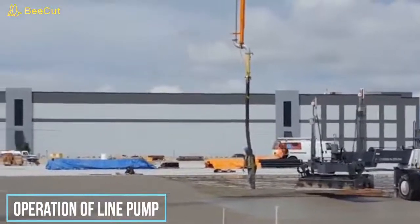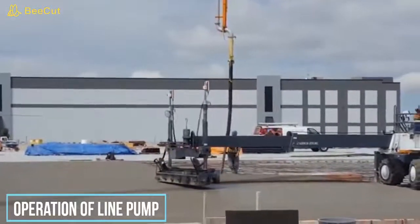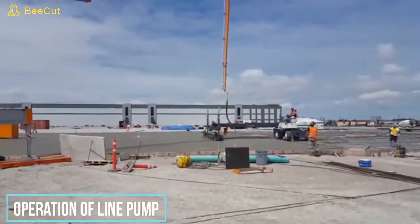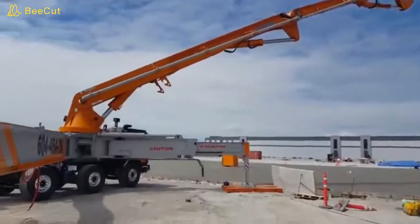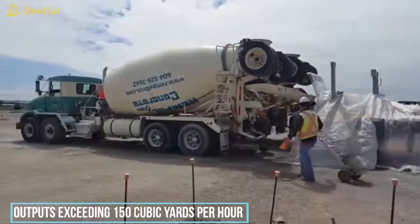They are also used for repairing underwater concrete, filling fabric foam, placing concrete in heavily reinforced sections, and building bond beams for masonry walls. Some hydraulic-driven models pump structural concrete at output exceeding 150 cubic yards per hour.